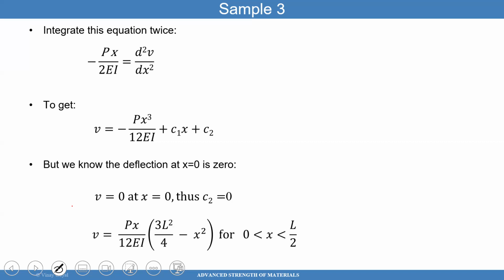You don't want to model every single blade. Maybe we can model a section of it that's repetitive, to save computational time. With an aircraft, a lot of times they cut the model in half and only look at half because that's more computationally efficient. We do this for a lot of other applications where symmetry can be very useful.